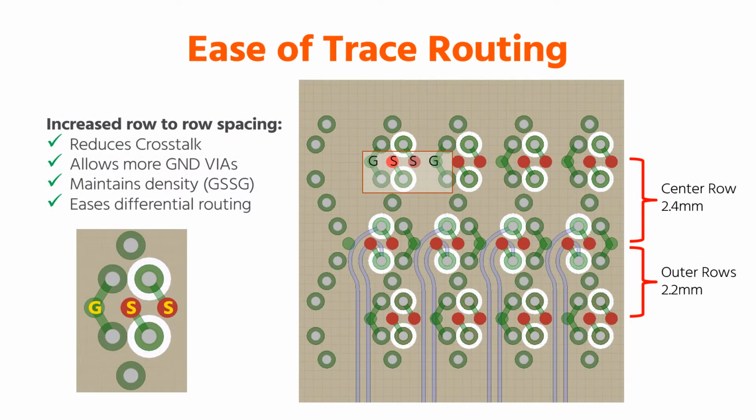During development of the spec, we put a lot of emphasis on optimizing everything we could. Even the trace routing from the connector to the boards on the module and on the carrier have been tested and simulated. You see also the ground schemes here. The dots you see in the graphics, ground, signal, signal, ground, that's one differential pair.